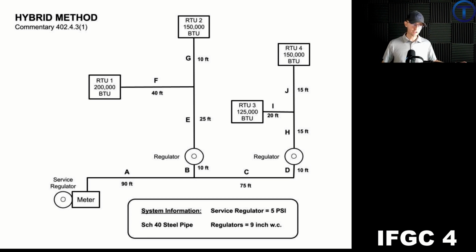We're going to run 1/2 inch for everything from the meter to the regulators. And then we've got anywhere from 1 1/4 to 3/4 on these branches leading to the rooftop units. Nice work.